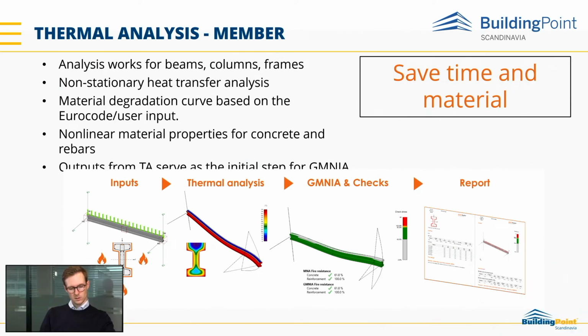There's also now thermal analysis in the member application. So yeah, a material such as concrete changes its physical properties when exposed to fire, and finding out the temperature distribution across the cross section, and reducing the properties of concrete and steel, is a difficult task that most engineers solve with simplified methods that are very conservative or even fail to solve these problems.